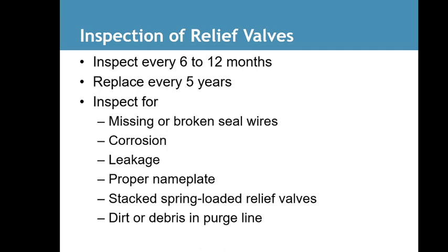There's normally a requirement for inspection of relief valves. You have to inspect every 6 to 12 months, replace every 5 years, inspect for missing and broken seal wires, corrosion, leaks, proper nameplate, stuck springs in spring-loaded relief valves, dirt and debris in purge lines.